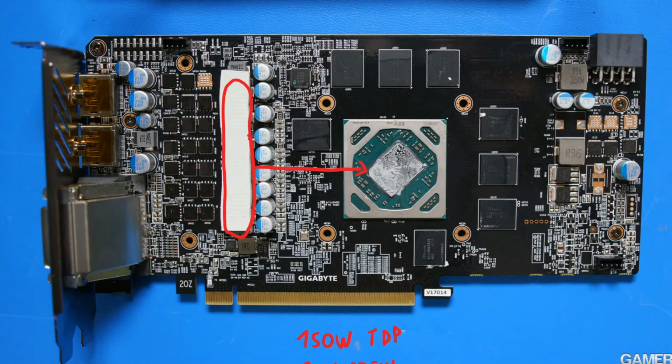And because AMD is using the V-Core inductors for power measuring, you only see how much power is pulled by the core. Everything else on the card is not factored into that power reading and essentially has no power limit. And that's also where all this news came from, where when the RX 580 launched, people noticed it was overdrawing the PCI Express slot rather heavily, because you only know how much power the core is pulling, you don't know how much everything else on the card is pulling, and therefore you can't really limit the power consumption. So yeah, that's how it works on AMD.